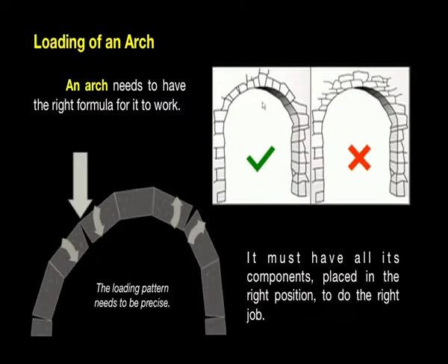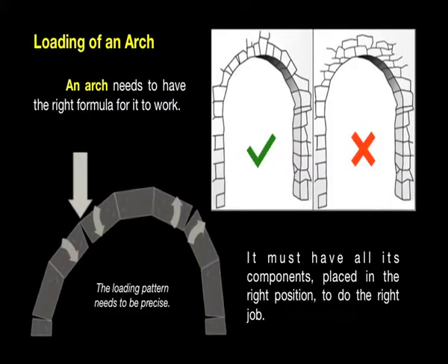And especially when you apply load onto an arch, you have to be very careful, because the load has to be applied directly at the middle or on top of the keystone. If the load does not act on the middle, what happens is, you can see in the picture in the bottom left corner, the load applies onto this stone, which means that the stones on this side cave inward, whereas it creates an upward thrust on this area, thereby dislocating the entire shape and structural integrity of the arch itself.